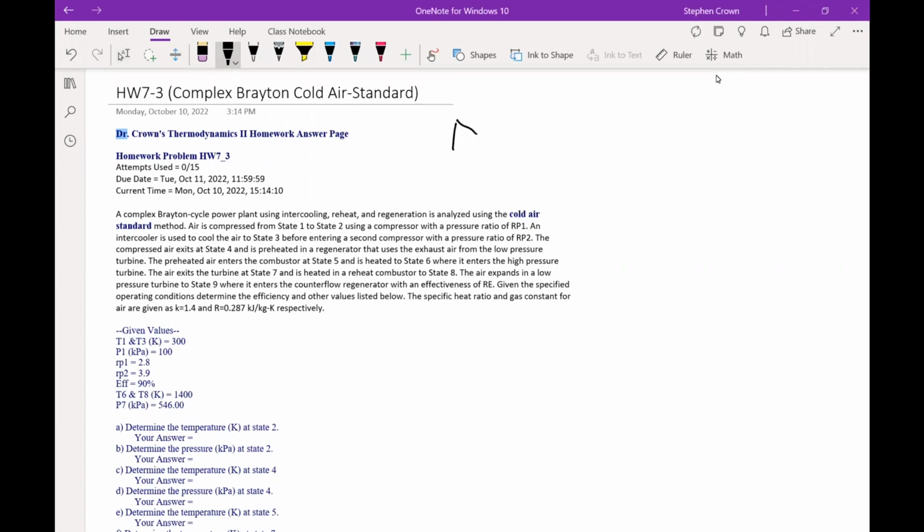So we'll start with our first compressor, call it compressor 1, and then we'll cool it. Let's call this the heat exchanger. In this case, we have Q out. And it goes into a second stage of compression, compressor 2. Now we could do several of these, have another heat exchanger or an intercooler, and then have another stage of compression. But we'll stop with that.